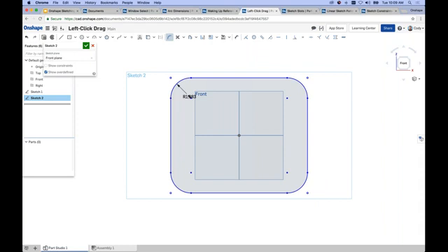All right, so I see a few questions. In our company, we go with configurations and equations. So what is the best way to design the whole project, in the Part Studio or assembly? I would do my best to avoid having everything in a single Part Studio for performance reasons. It depends on the size of your project, but I would consider strongly the assembly. Which means you'll probably need techniques like in-context design and so on. If I want to change the same part in all assemblies, what's the best way to do that? It would be to edit it from that Part Studio.